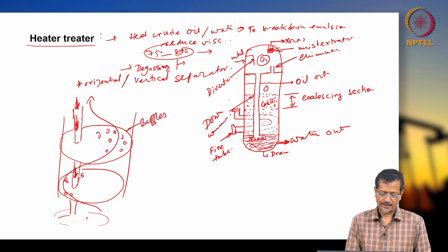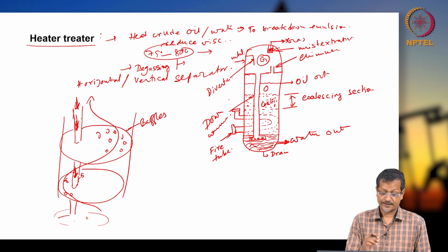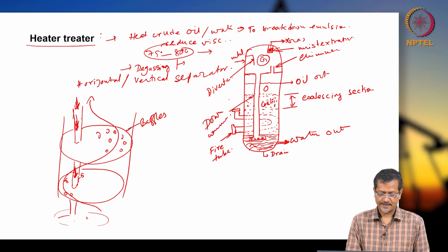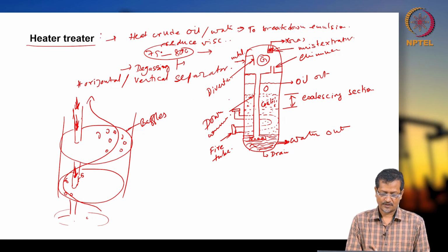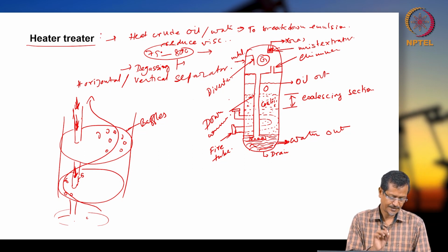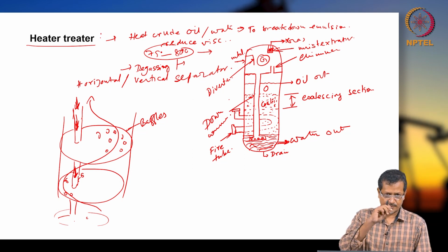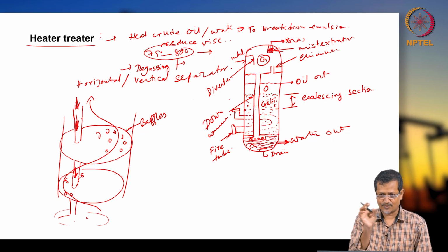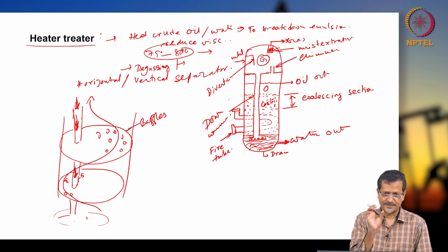When a larger amount of gas is separated, turbulence increases and coalescence will be a problem. Small gas bubbles have attraction for water and for surface active material, so small bubbles are created, and the surface active agent will not allow them to collide. So that will hinder your separation process.